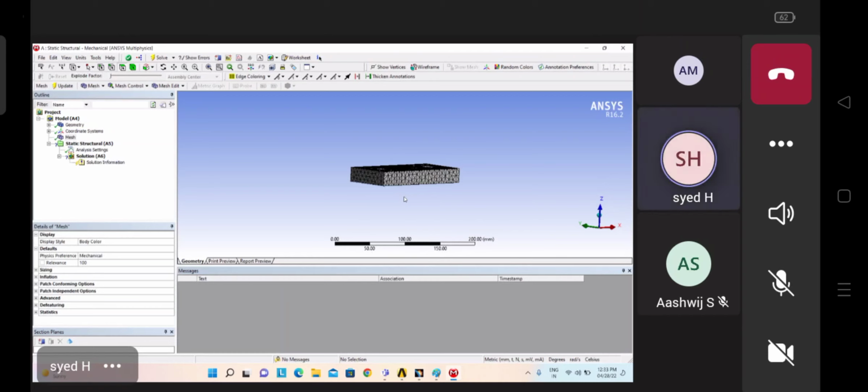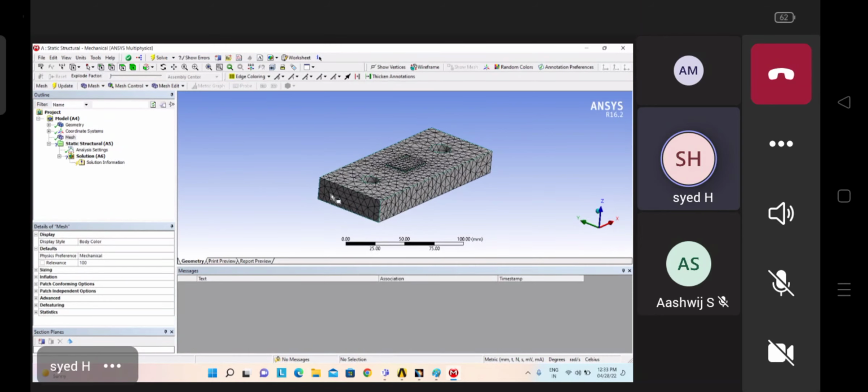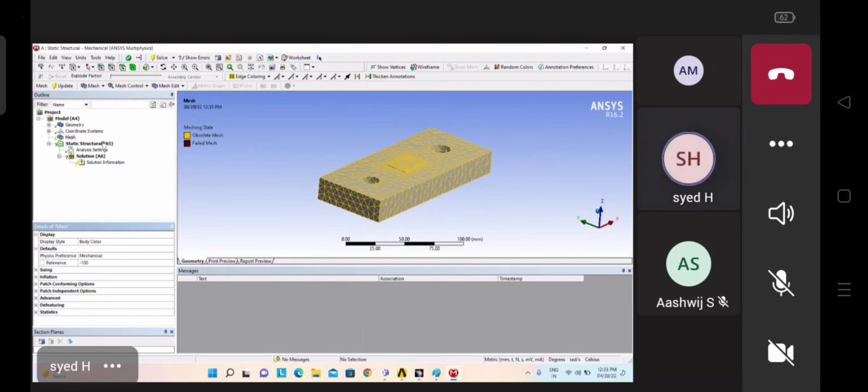So that is the reason we have to choose this option. Suppose, for example, I have taken this mesh here. It will take around 10 minutes, I am just taking an example. Whereas when you go for the negative value, if you decrease the relevance and the number of elements is reduced, it will take only 5 minutes to solve, because we don't have that many elements. So we have to think and consider everything while performing the meshing. I am changing this to the negative side and updating.